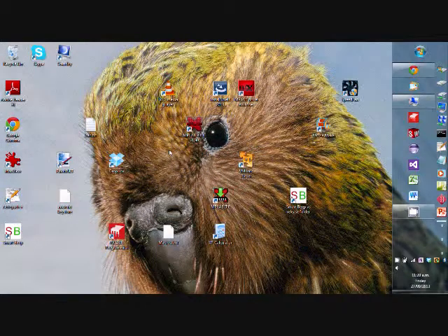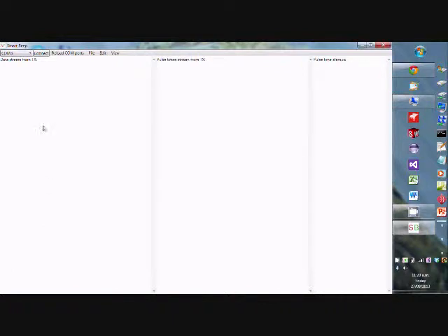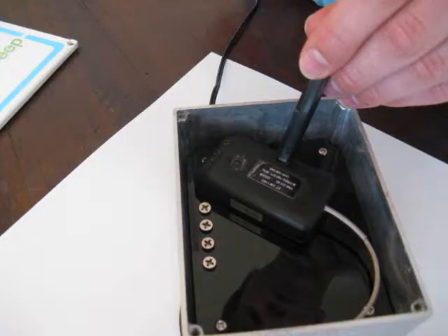To use the SmartBeep system, first open the SmartBeep application using the desktop icon. Next, choose the COM port that the SmartBeep hardware is connected to. This can be obtained by looking at the device driver installation dialog in the notification area. Turn the transmitter on using the process outlined earlier. Immediately after you have turned the transmitter on, click Connect to connect the SmartBeep application to the hardware.